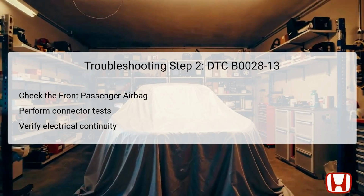The second troubleshooting step for DTC B0028-13 involves a thorough inspection of the front passenger's side airbag. Begin by disconnecting the connector and ensuring it is free from any visible damage or corrosion.